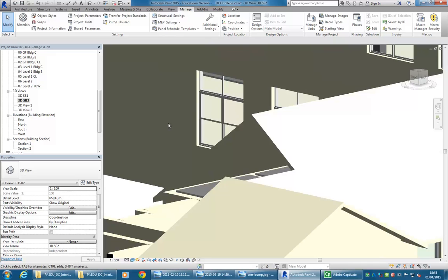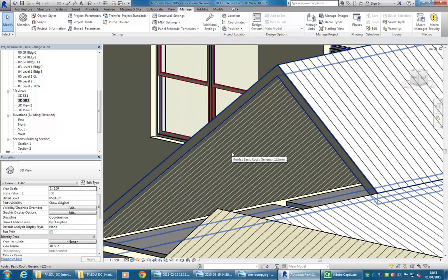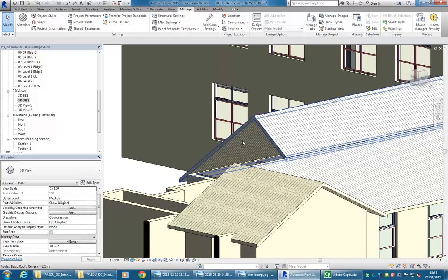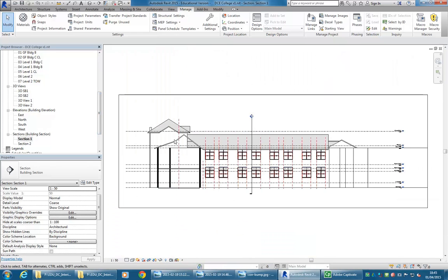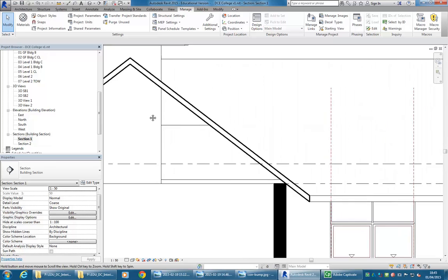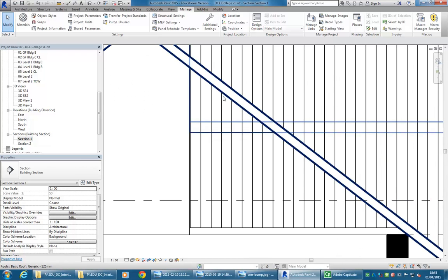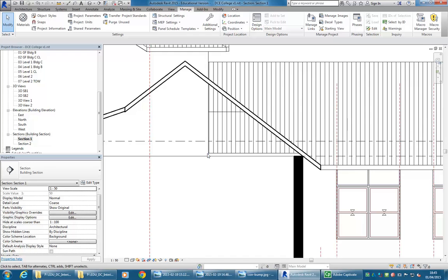But then also, it's got it on the underside with those lines because I set it as a surface pattern, the vertical parallel lines. Now that's okay because we shouldn't see the inside of the roof anyway. If we see that, we've got a problem. Because you'll have a ceiling to block the view of that in the interiors, in your perspectives. In the section, you won't see it either because it'll just be cut. Maybe you'll see it actually sometimes on the underside in situations like this, but you should really have a wall coming up to block that in the end.